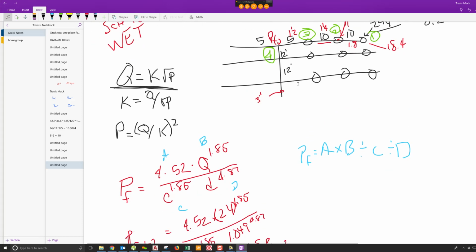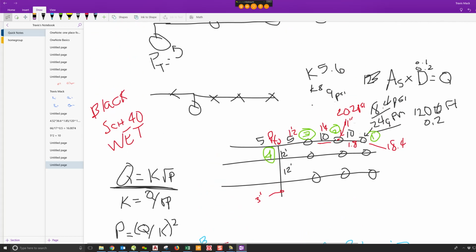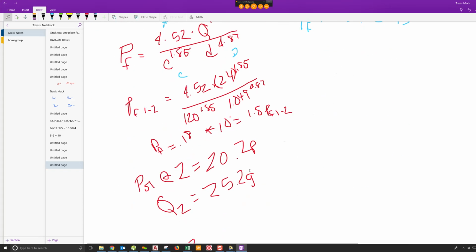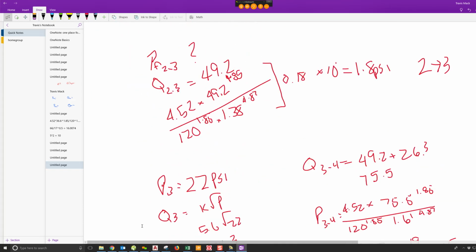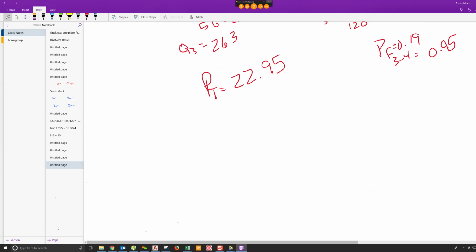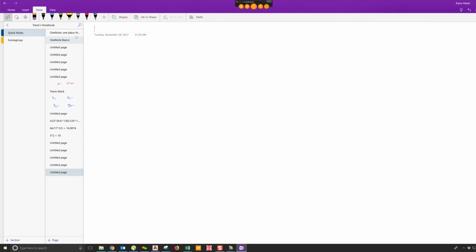If you don't understand what all this is doing, is there something in NFPA 13 that says that you can't use the K factors to balance out the flows? So if we were to do this with an 8.0 K factor, here, let's try that. Let's do this exact same thing with an 8.0 K factor. Let me just start a new page.